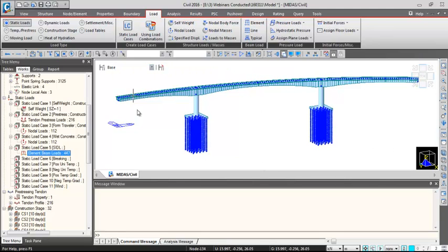Okay, this is done. Now moving on to the braking load. Braking load, in accordance with the clause of IRC6, acts at 1.2 meter above the deck location. The major bending moment contribution due to braking load would be for the pier, and the impact on deck would be less. So what is taken in this case is the braking load is calculated for one span, and it is equally distributed on either support of the span. So that way the braking load was calculated.